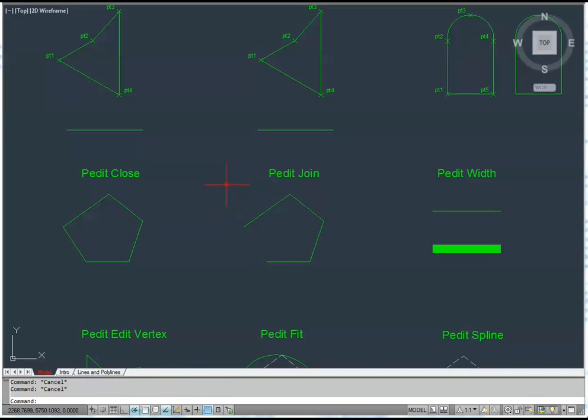If I go the other way, starting from the left and moving to the right, it's a blue rectangle with a red solid line, and it will only select objects that are entirely within that marquee. So you see two lines that it's crossing, it won't select those. There are other ways of selecting objects, but we'll look at that again in another tutorial. That's the filter and the quick select methods.